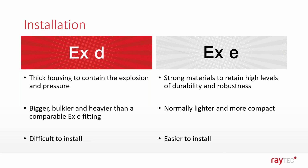In contrast, an EXE luminaire is preventing and not containing. While it still needs to be designed using durable materials, which are capable of withstanding the environment and the challenges that come with it, they can be designed to be much more lightweight and user-friendly from an installation perspective. More lightweight, more compact for applications where space is confined and hence easier to install.